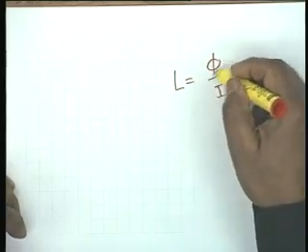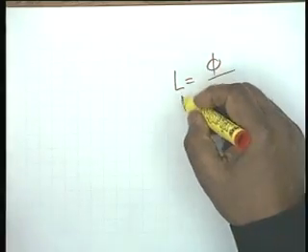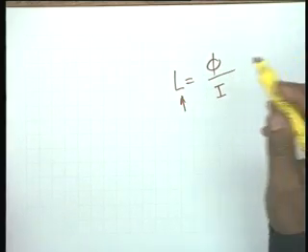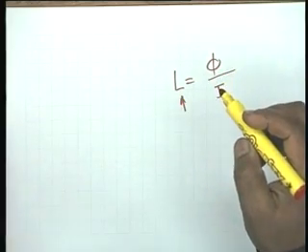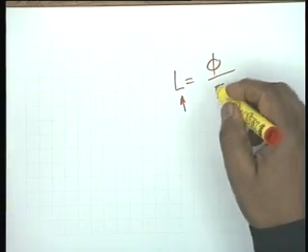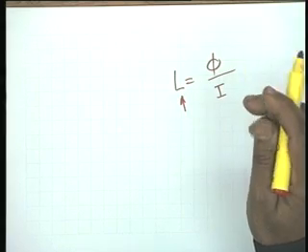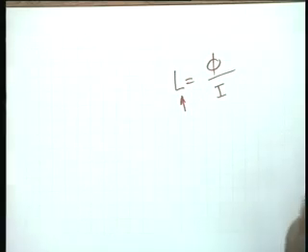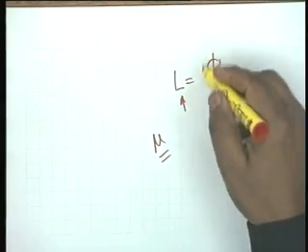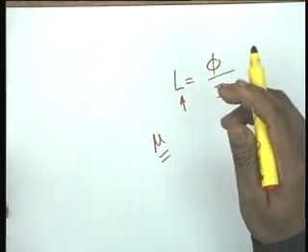And generation of a reasonable amount of flux. You see, if you want to make L high, then you should make the flux high. Okay? For the same current, you should make the flux high. Now, if the medium is not changed, that is, medium permeability remains the same, for generating a large amount of flux you require a large volume, which is not available in integrated circuits.